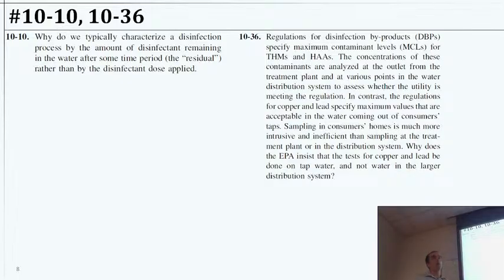So in that case, it's extremely important. In the case of a plug flow reactor, it works a lot better, but it's going to be safer to apply it and assume that some of that chlorine went away really quickly, or the ozone or whatever. So some of that will be instantaneous demand, some of it will be demand over the course of the plug flow reactor. The safest way to design it then would be to treat it as if it's reacting with the lowest amount of concentration that we know is in there for the entire time. It'll get better treatment than that, but that's the safe approach.